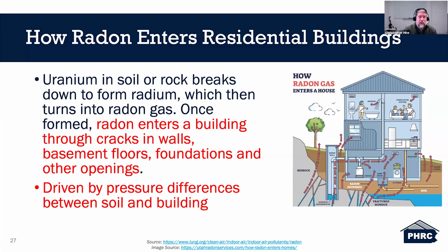But if you had the opportunity to print the handouts or you want to make any note whatsoever, please note the second bullet point: radon enters, it's driven by pressure differences between soil and the building. Okay? It's driven by pressure difference. So as we continue through today's presentation and we're talking about different strategies, let's think about how those strategies can impact the pressure difference, and how that could adversely affect the introduction of radon into the structure.